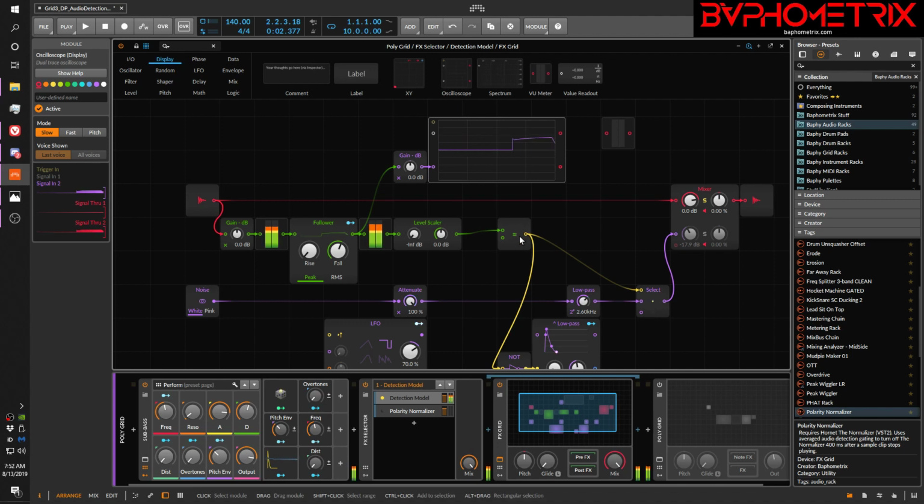this can still work, but a lot of times it makes the comparison stay active for too long when it falls, because there's a fall time over here. Look at this little graph and see how it has a curve. It has a fade out on the fall. We have to push the fall up in order to get the signal to just come up here and stay up here. But then when you let go of the incoming signal, when it stops, it takes a few milliseconds for that signal to finally fall back close enough to 0 to trigger this and effectively say, yeah, you're pretty much 0 again.